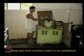Now, while interacting with a machine, for different body parts movement, the body should match with the machine dimensions. Like if he stands here, how much he can extend his arm, what is the normal height of these things, so that he can work. This is the main working area. It should not cross the heart level normally, it should be below that.